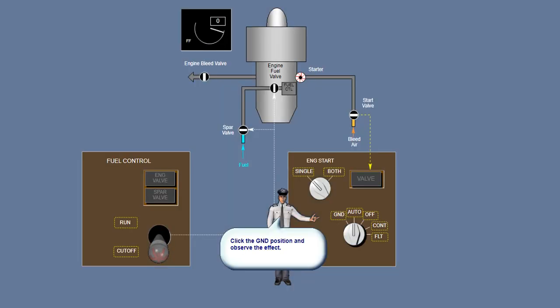The engine start valve light illuminates briefly as the valve moves to the open position and then goes out. You will likely not notice this momentary illumination. However, if the start valve fails to open, the valve light will illuminate steady and the ICAS advisory message left or right engine starter will display. These same indications will also appear if the start valve fails to close when the start is complete.